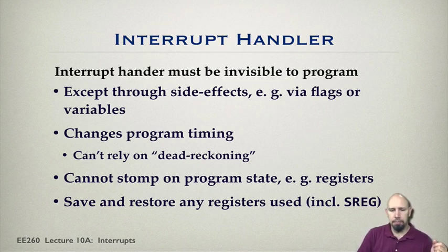And in the loop program, you can set things up. For example, you could say the variable C is equal to A plus B. And if C is a global variable, in your interrupt service routine, you could change, for example, the variable C. And then when it returns back to the main loop program, you find that C is not equal to A plus B. And you may be expecting it to be equal to A plus B. And so you can run into some kinds of problems. And so you need to be careful when writing interrupt service routines that you don't accidentally mess up a variable that you're intending to use.